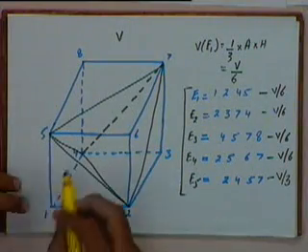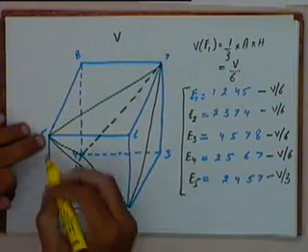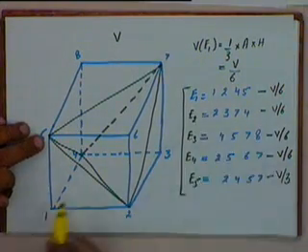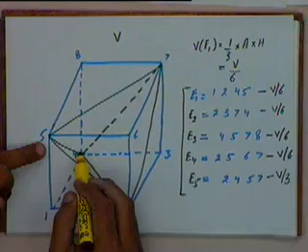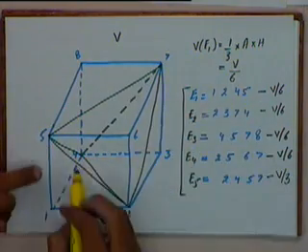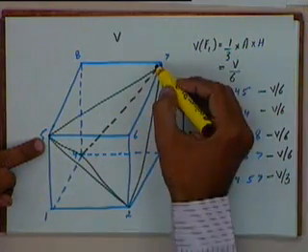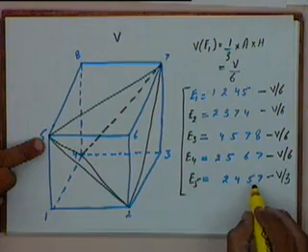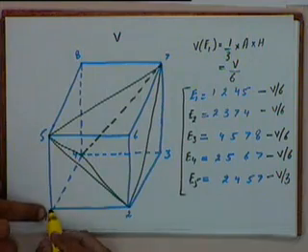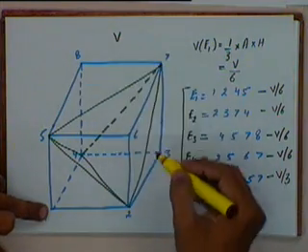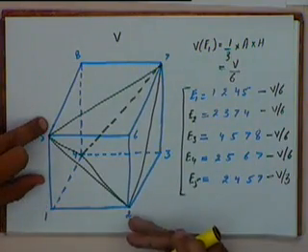where we said that if we have this cube given by 8 nodes, 1, 2, 3, 4, 5, 6, 7, 8, and we want to split it into tetrahedral elements, we can take elements like 1, 2, 4, 5; 2, 3, 7, 4; 4, 5, 7, 8; and 2, 5, 6, 7; and the fifth one is 2, 4, 5, 7, which is inside all these 4 elements. These 4 elements are basically at corners 1, 6, 8 and 3.